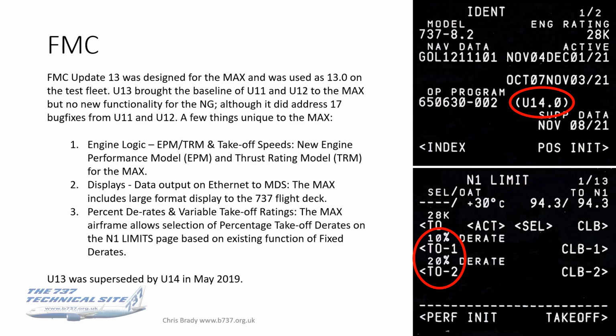and you can pre-select your airfield runway combination, and it will automatically then give you the appropriate D rate for operation from that runway, which is useful to save the company money and engine life and what have you. Rather than blasting off at 28k every time, then you can use these fixed D rates. And again, these are fixed D rates. This is not assumed temperature thrust reduction. You can do assumed temperature thrust reduction on top of the D rates.